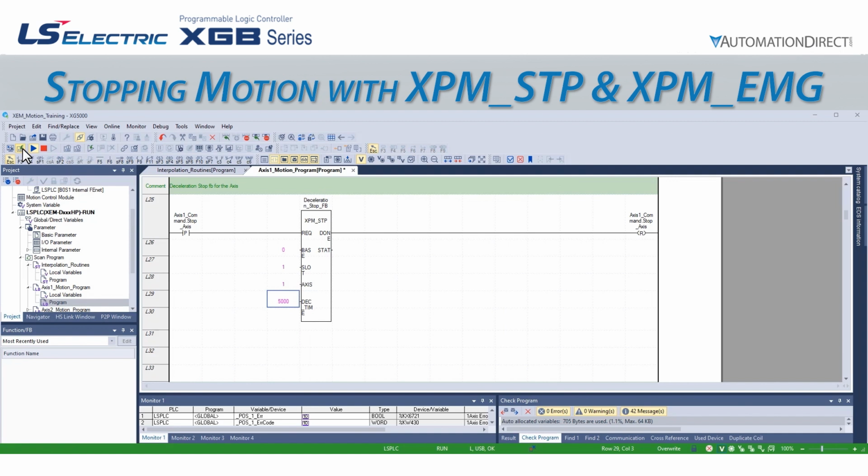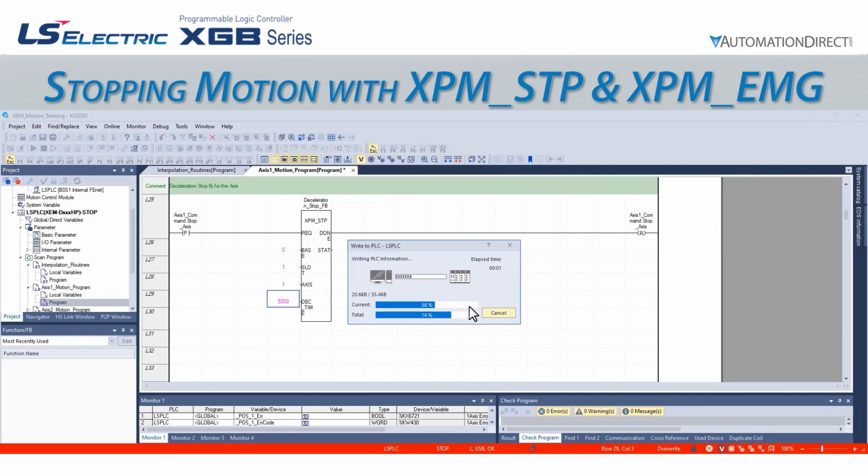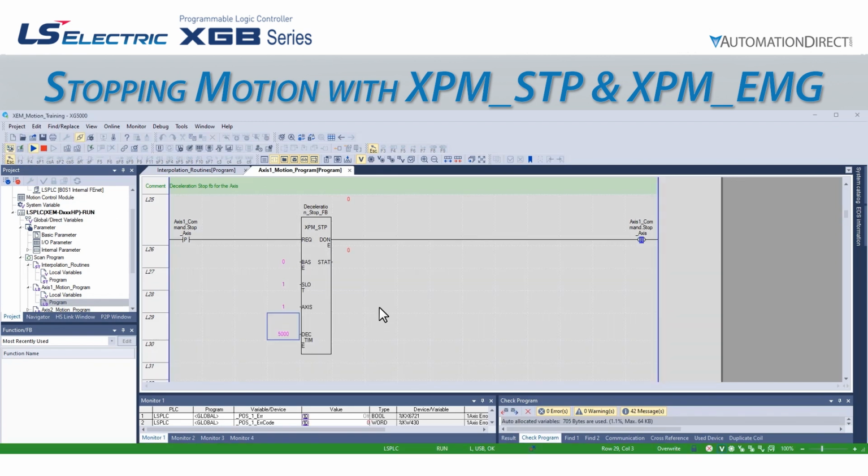Write this change to the PLC, and then re-enter monitor mode. Our emergency stop command is on line 35 of the code. To view the deceleration for this command, we need to open the XGPM software. We can do this from XG5000 by going to Tools, Position Control.